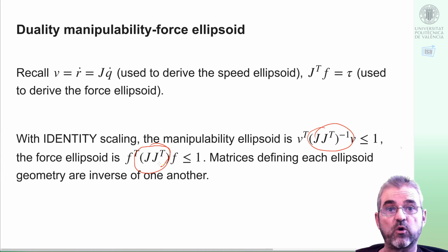So the Jacobian magnitude, or singular values, more on that later, will be inversely proportional to the applied end effector forces. On the other hand, as in here we have inverted, we are sort of dividing by the Jacobian, so double the Jacobian, double the speed. Then in this case, the speed magnitudes are directly proportional to the Jacobian magnitude.